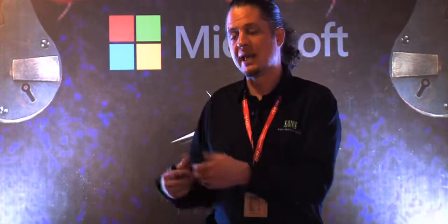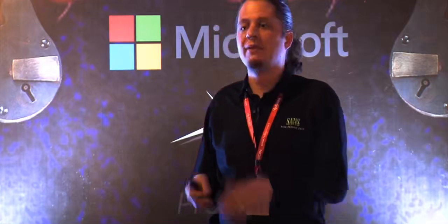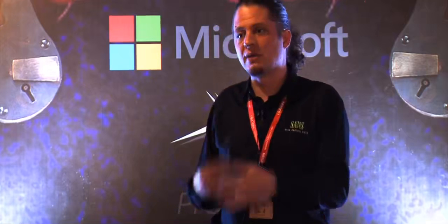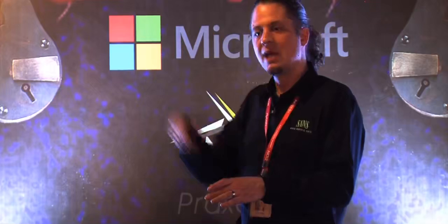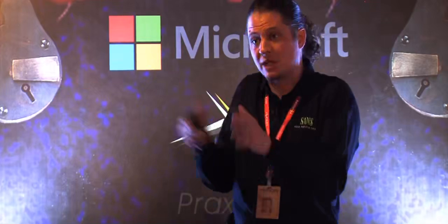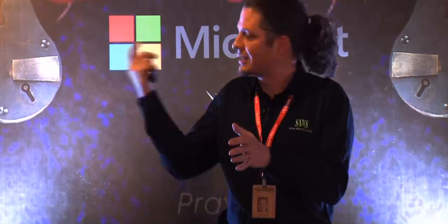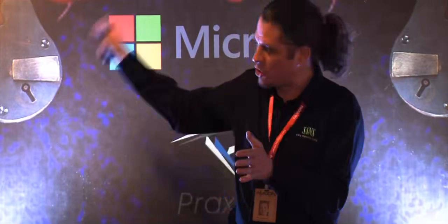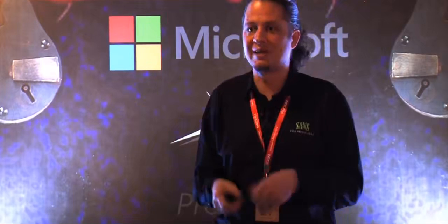If not, for instance, a lot of the field technician interfaces, you'll have a serial interface on one of the field devices, and it has a proprietary interface on that. Often you just go through the normal process of reverse engineering. I find a way to be able to capture and analyze that information, and then I go to the control system server or the interface, whatever, somehow to be able to manipulate the traffic, and I send a request or use a function that I know, and I try to capture just that one single request that I made. So using that information, I look at the data and try to understand what I just did in that interface came through inside of this message, because I know I just did something, I know it came in this message. Just use the process of reverse engineering to try to figure out exactly what bits represent what types of information.